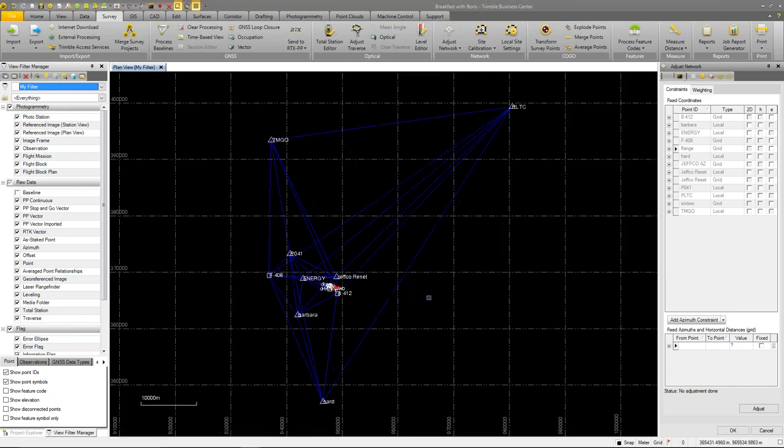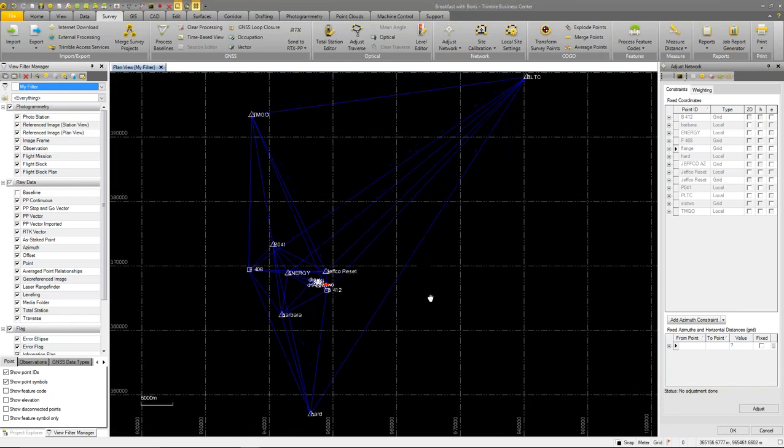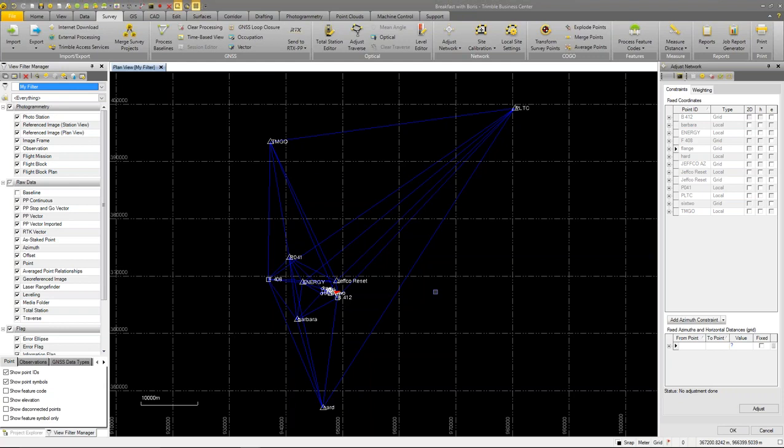But if you leave that bad horizontal coordinate value for point B412, as Ryan is suggesting here, won't that skew the adjustment? It's not a control quality coordinate that it's yelling about. So no, when I have my final adjusted values that are assigned to these points, they're going to rule over anything other than control quality in the network.